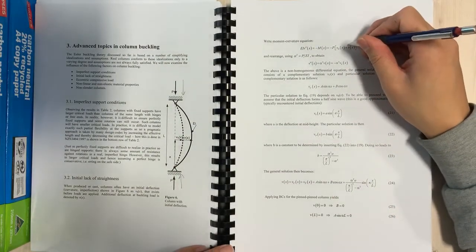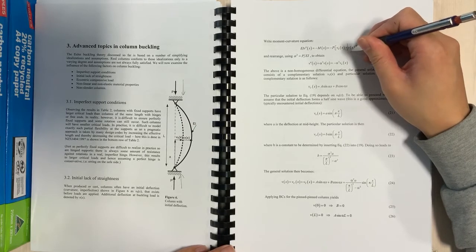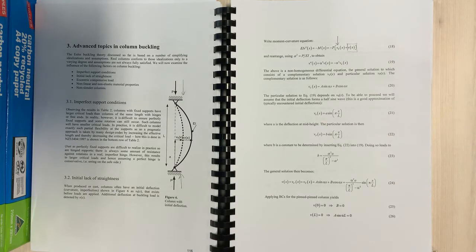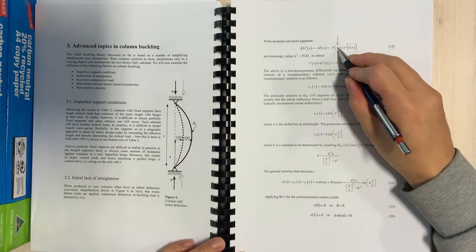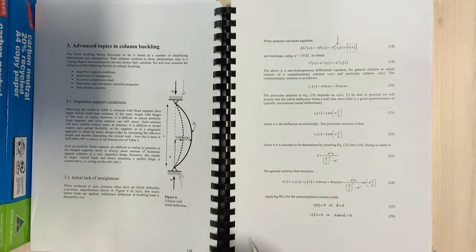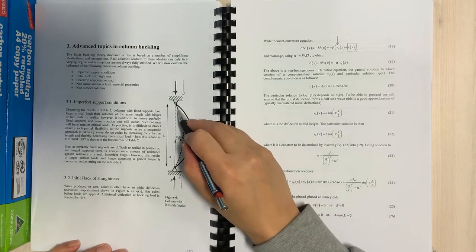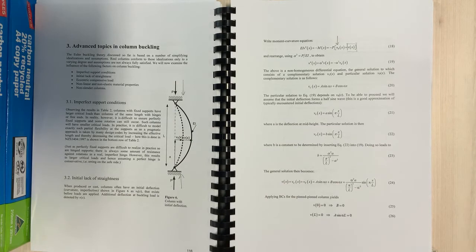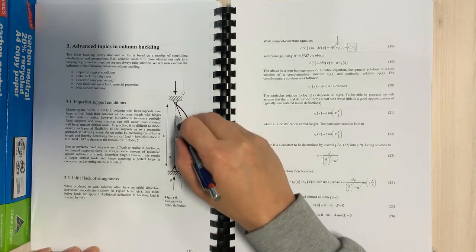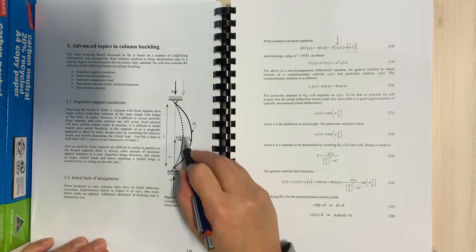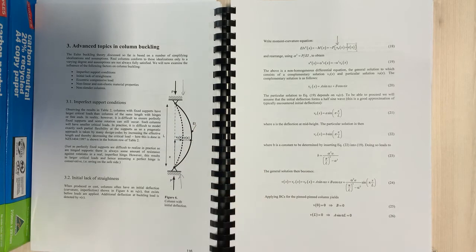Now we've still got this bit here, which is the v of x, but now we're going to see if we can develop some theory where we can introduce v naught x, and we're assuming that this is the initial imperfection. So we say that the column is not perfectly straight and there's a very small imperfection. Sometimes that imperfection is about L over 1,000, so a 1,000th of the actual length of the column is the initial imperfection. And note here that we're assuming that the initial imperfection is also a sine function. So rearranging this,